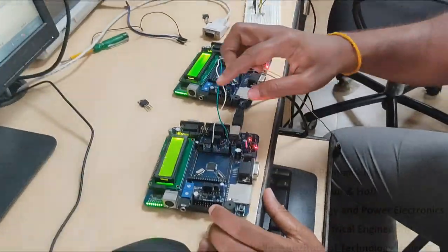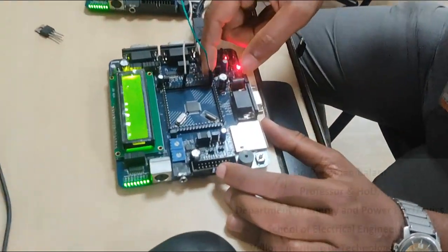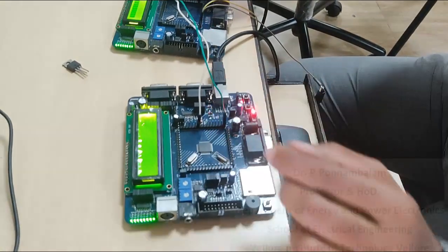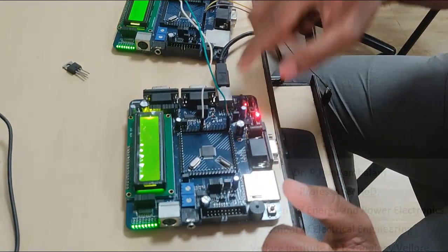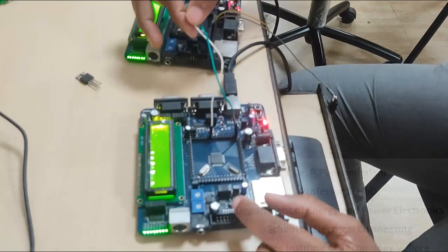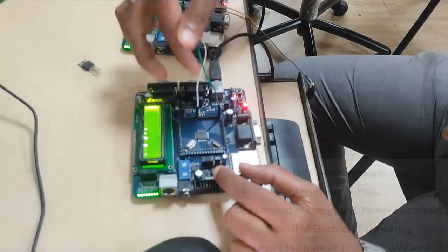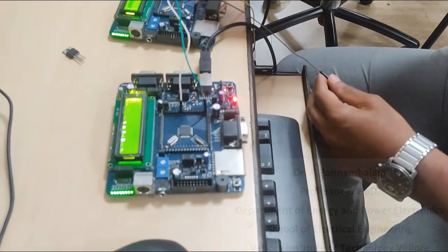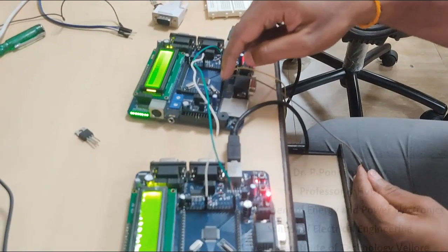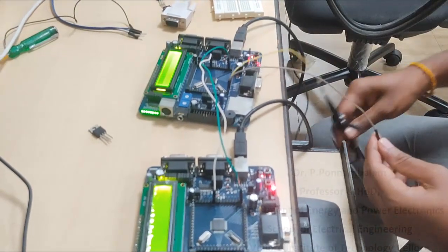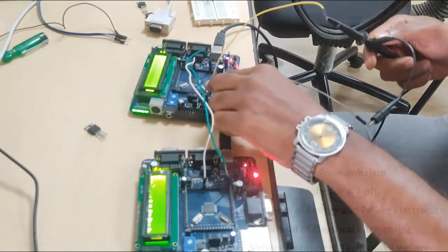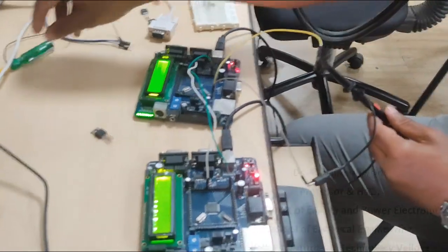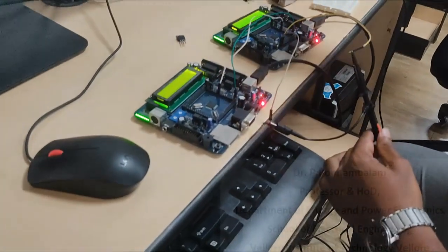Okay. Now over here, this is the J3. In J3, as I've already told you, the number 1 pin I am connecting to the J3 number 2 pin. This transmit is connected to the receive, and this is the ground pin. 10th pin to 10th pin, I have connected the ground pin, and from the J2 connection I am taking the second and third pin. The third pin should be connected to the positive of the probe, and the second pin to the negative of the probe. Right. So now the connection for checking whether the transmitting is happening is done.